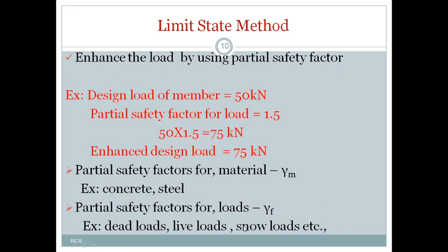It depends on which area we are constructing that particular structure. If the structure is constructed in a snowfall area, then we will consider the dead load. Generally dead load is the self-weight of the member, and we check whether any live loads are there or not. And definitely, as it is a snowfall area, we will consider snowfall. That means the total design load can be calculated as dead load plus live load plus snow load. And what is the enhanced design load? That will be calculated from the codal provisions.